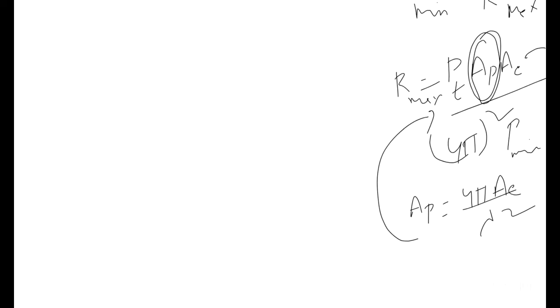Now we will see the internal functioning of each step by step. So the pulse modulator is producing pulses. The transmitter consists of microwave oscillators such as a magnetron. This magnetron is switched on and off, meaning here we are getting pulses from the magnetron. This pulsed sine wave travels to the duplexer, to the antenna, and is radiated into space. After radiating into space, it comes back to the receiver. So the first part is completely the transmitter part.